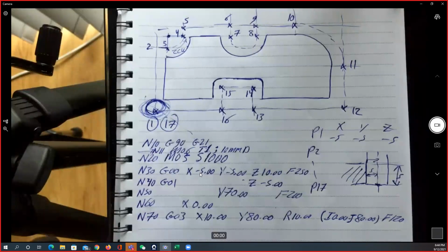If you follow this step-by-step tutorial, you can put your code in, and then you will be able to simulate the work and get the shape cut. Just remember that the dimensions for the X and the Y are clear, but the thickness is going to be 5 millimeters. That's what I would like you to do later in your checking.